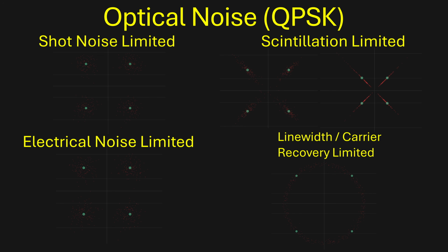For example, if you attempt to use low baud rates with a coherent detector with a wide line width, the random phase fluctuations of the laser will shift significantly over individual symbol periods and cause phase rotation and phase errors. This is one reason why low data rate deep space links will typically use direct detection. We will do simulations of these later on, but for now we can simply estimate power received and compare this to the published power sensitivity requirements for commercial transceivers.